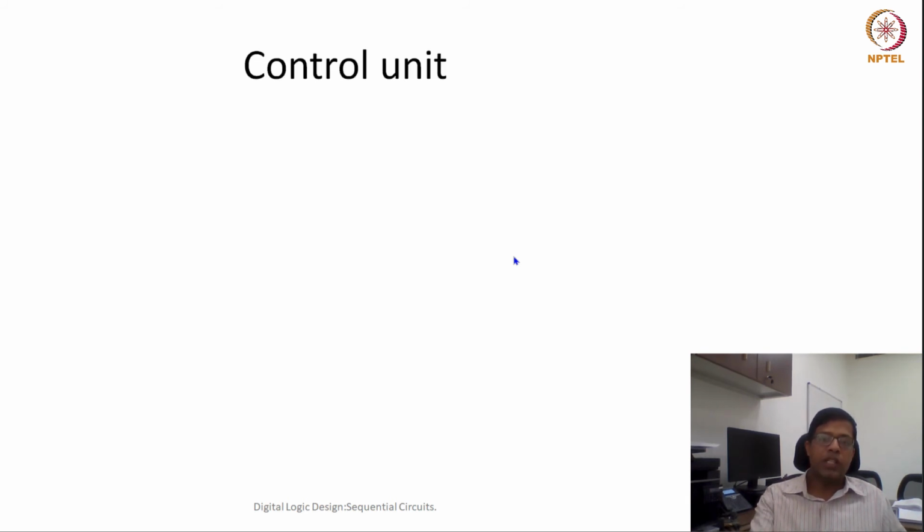So let's look at the finite state machine. First of all, for the finite state machine, let's very clearly specify what my inputs and outputs are. My input is, let's say, ST, start, and my output is SH, shift. So this is the input and output of the control system, the controlling part, or the input and output for my FSM, finite state machine.